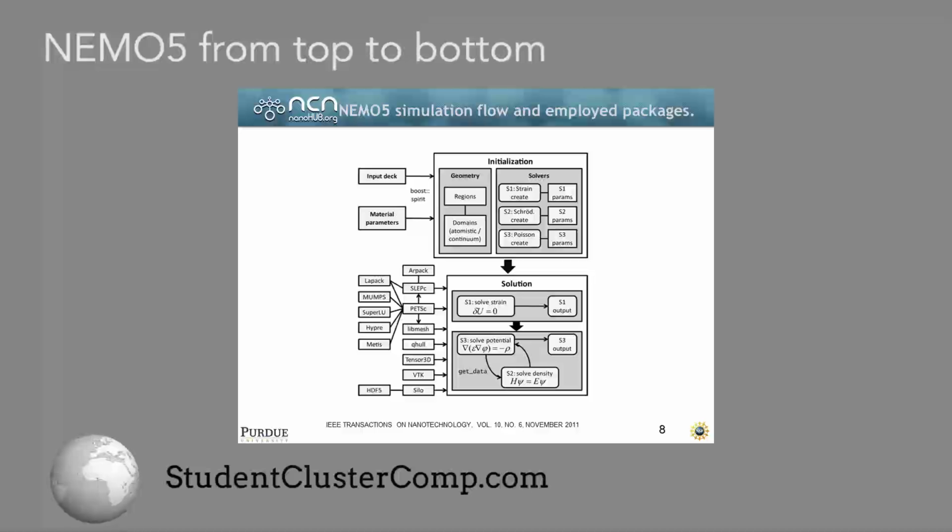Depending on the simulation that you want to run, you're going to set up different solvers. And without getting into too much detail, there's some information in the NEMO5 manual that can give a better idea of what those solvers could be. For instance, Schrodinger or Poisson solvers. And I would assume that you'd advise the teams to be somewhat familiar with that manual and have it close at hand. Yeah, we've been trying to do a lot of work on it recently. But it's probably the first place to look.